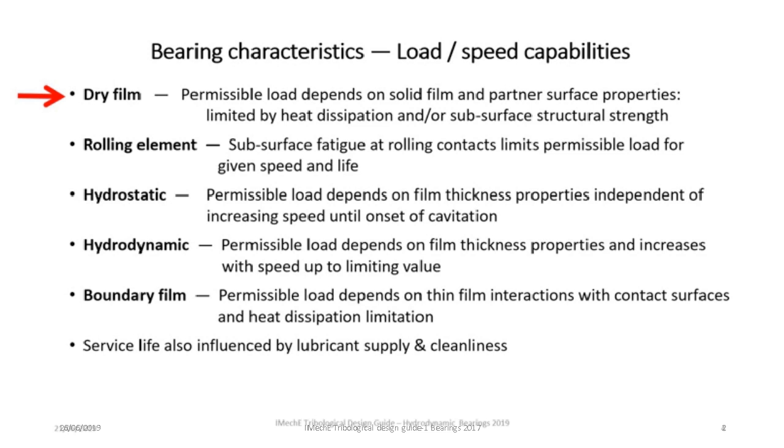The life of rolling element bearings is invariably limited by fatigue of one of the races. The location of the fatigue failure can be either beneath the surface of the material or at the surface, initiated perhaps by over-rolling a hard particle.